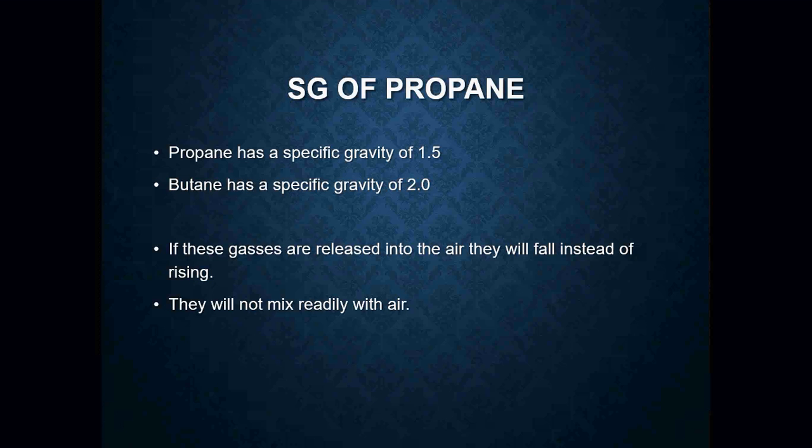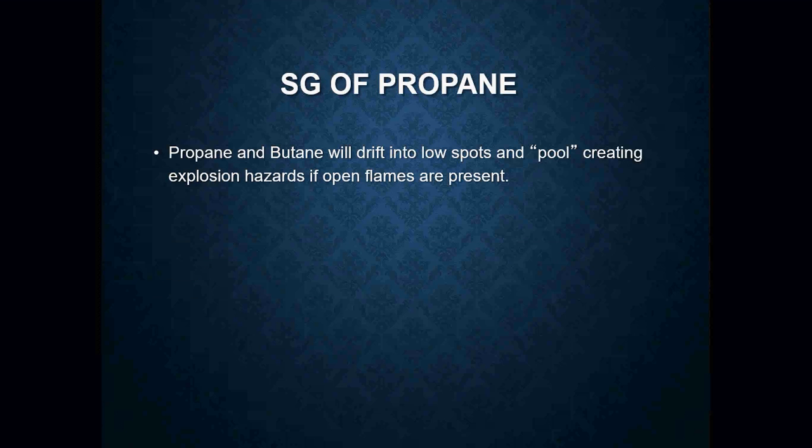Okay? If these gases are released into the air, they will fall instead of rise, and they will not mix readily with the air. Okay, butane and propane will drift into a lot of your low spots, or it's going to pool, creating an explosive environment if open flames or spark is present. Now, I've seen a couple of instances with propane leaks and have seen some of the damage that